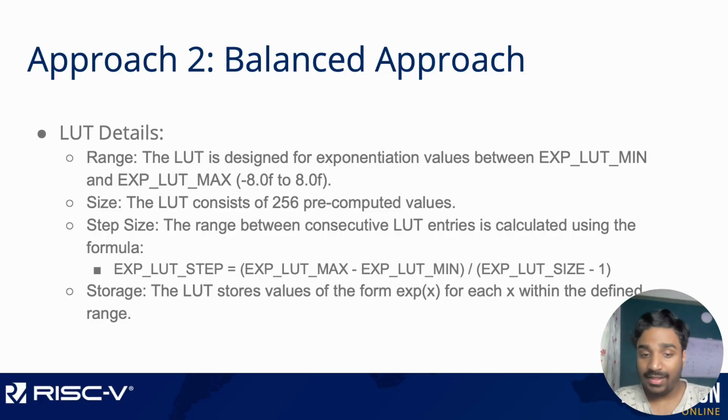On the details of the LUT implementation, I decided first on the maximum and minimum values which the LUT table could support, and I decided on the number of values which the LUT table will hold. This can be modified as per what approximation we are aiming to achieve, and what error rates we are aiming to achieve. So we can write a script for doing this. I personally wrote a Python script for generating this LUT.